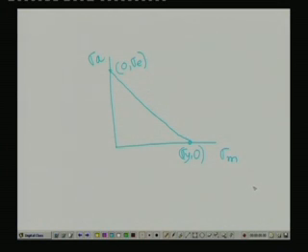So, if we consider the equation of this line, then you can see very easily that we get an expression something like this: sigma A minus sigma E, just an equation of straight line, equals 0 minus sigma E over sigma yield point minus 0, times sigma mean minus 0.